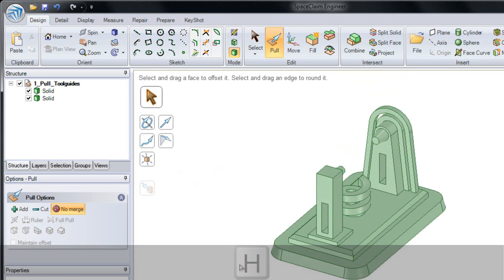So in this section, use our tool guides of sweep, revolve, and draft to make 2 sweeps along our angled protrusion. Use revolve to make a helical solid, making sure to check the No Merge option, and then draft some of the side faces.